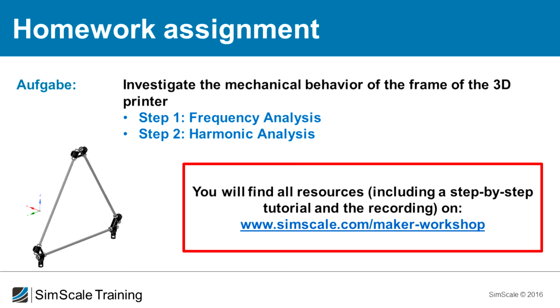And then you are asked, on this next level, to create a harmonic analysis based on these results. You can reuse the mesh for this, so you don't have to create a new mesh, and you have just to adapt some small things. And we will also provide for this a step-by-step instruction.